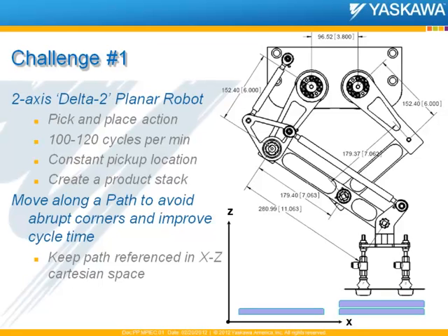All right, well, let's get into the kinematics. What we mean by kinematics is the ability to control other mechanisms besides just the standard, traditional XY, XYZ. There are some applications where it's a benefit to not have a belt-driven or screw-driven type system and instead use something a little bit different. So one of the mechanisms we're going to focus on today is a Delta II style robot. This is a two-axis robot. It operates in a plane of motion, so it's a fairly straightforward kinematic mechanism.